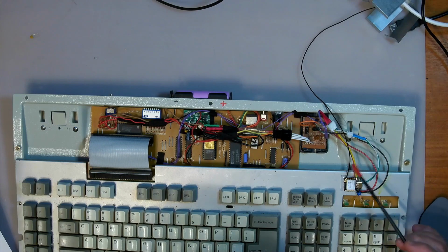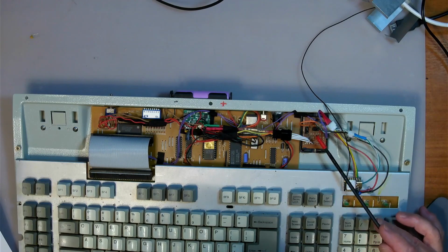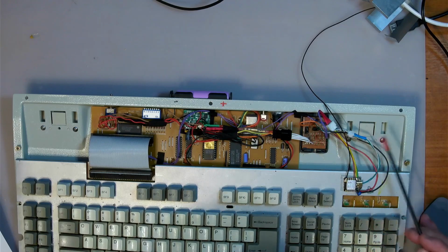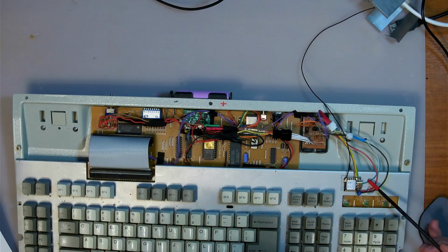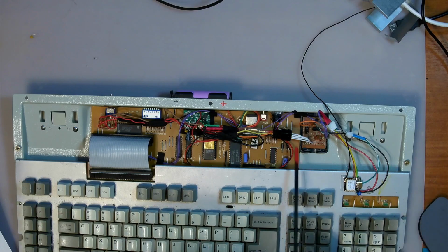So I actually crossed over those wires where previously was D minus. I made it D plus, and D plus and D minus, and lo and behold, it started working. And what happened is that as soon as it was actually making a proper USB connection, it pulled the signals high and allowed the data to come through, and it was outputting the data to this USB port here.